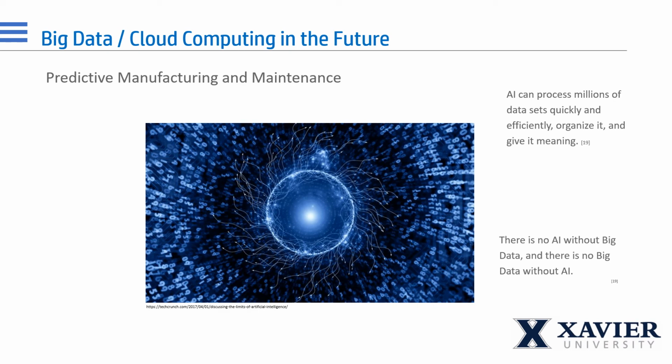If we think back to the motor we spoke about earlier, what if we combine our motor data and the maintenance and repair logs with the data logs of 100 or 200,000 other users of that same motor? Then we throw in AI to sort and organize it all out. At that point, with that amount of data, the AI can become predictive. For example, if 20,000 motors all showed a specific frequency immediately before they suffered a seized shaft bearing, the AI can analyze all those readings prior to the event and build a predictive model.